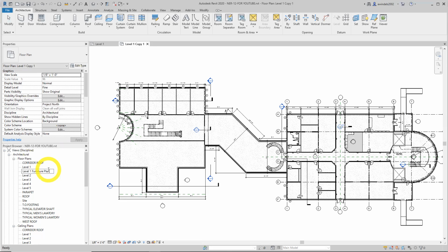Essentially, we're trying to make our next view based off the first one. So ideally, if you were modeling in Revit, to the best of your ability, you would try to make level 1 look how you want from a good base perspective before you go to level 1 furniture plan. That's not always easy to know when and how to do until you've maybe done a few models, but that's the general smart flow, is to get it looking 90% there before you create this. Going on to page 617.